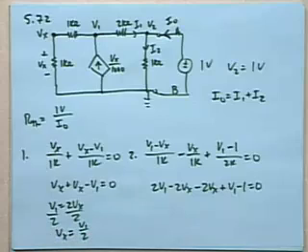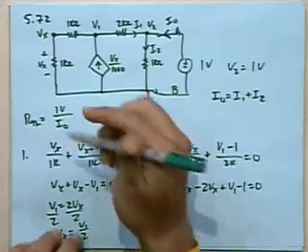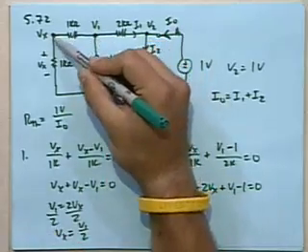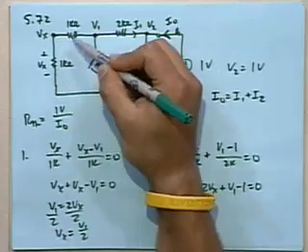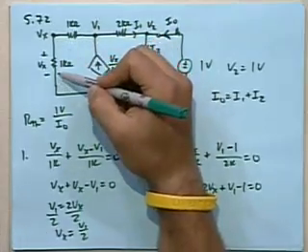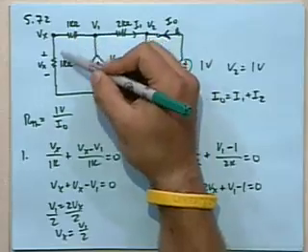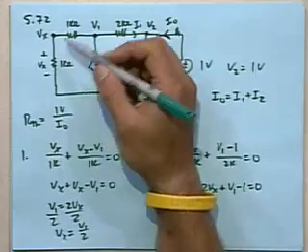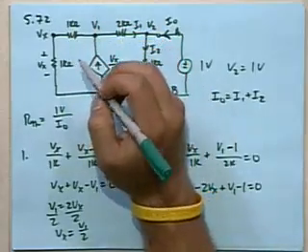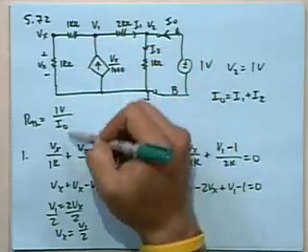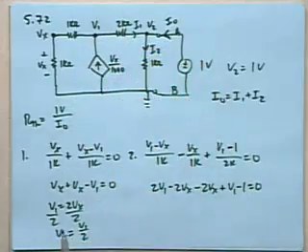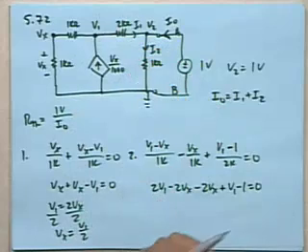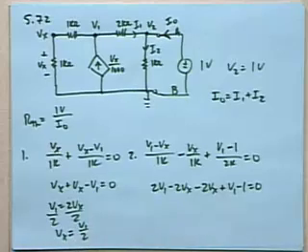And to some extent, that should be somewhat intuitive. I hope maybe just a little bit intuitive, because Vx was over one of the 2 1K resistors here. And the voltage V1 will be evenly distributed between these 2 1K resistors. That's what voltage division should tell us. So this is just mathematically working out that Vx is half of V1. And to some extent, hopefully, there was at least some intuition that you could have done that in the first place, just jumped right into that.